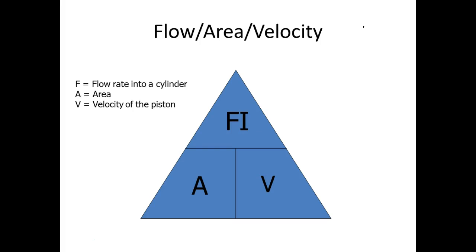So the size of your pipe does not determine the pressure. The size of your pipe determines how well you can maintain or get that flow. Yeah, but the sides have got to handle the pressure. The inside diameter of the pipe has nothing to do with the pressure. It determines how fast you can flow. What determines the pressure is the thickness of the walls. Y'all understand that, because that's trying to keep that pressure in.